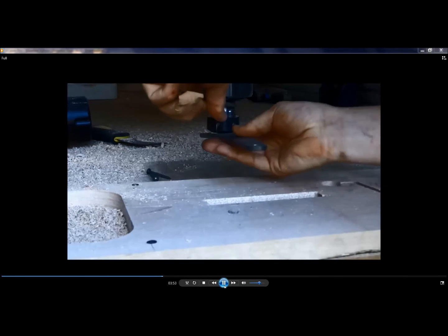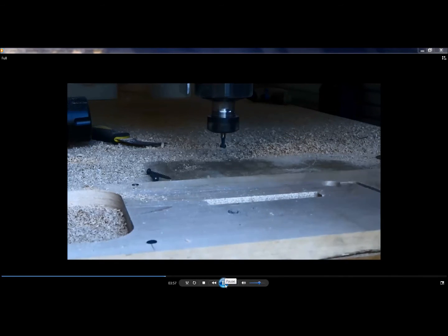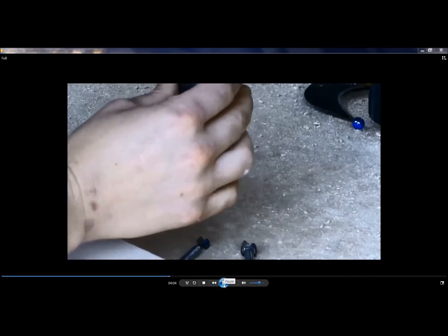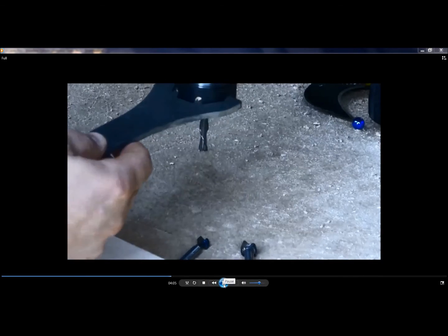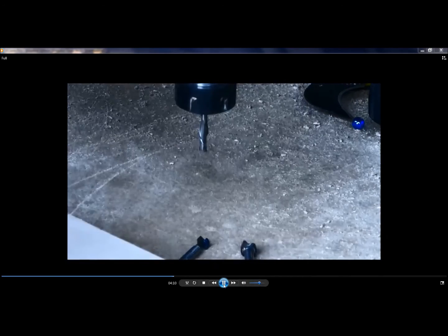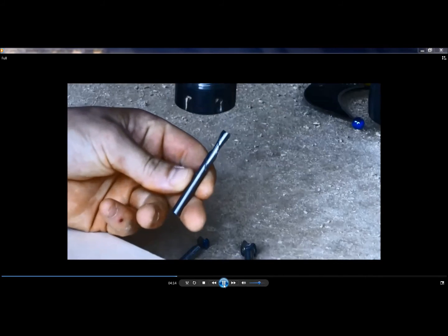And I've already cleaned out the spindle collet, put that in, and then zero that out. So notice that bit is wider at the bottom than it is at the top. If I was to try to plunge that straight down in there, that would wreck the material. And so besides the keyhole, here's another option. Since I was using round marbles for this, I didn't want to do it with just a straight keyhole.